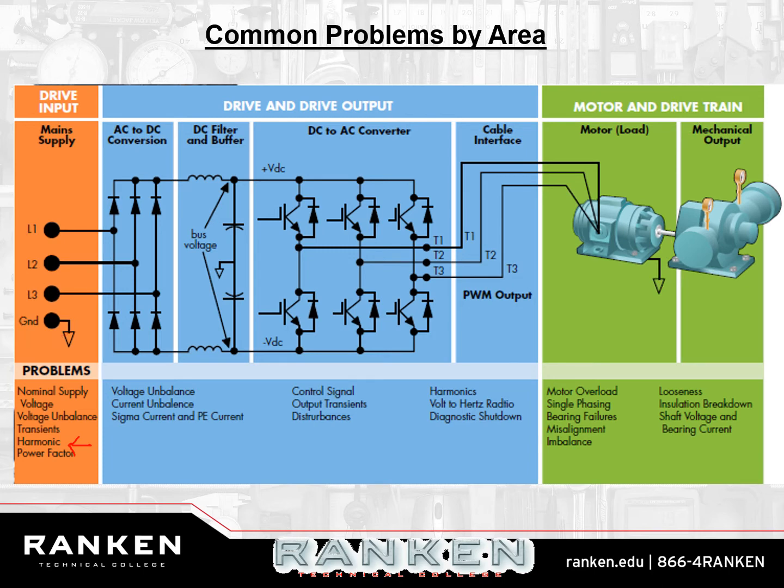The only thing that can stop it then are the little things, right? The actual control circuits. The control signals are the only other thing that can keep it from going. The drive isn't putting out power because somebody hasn't pushed the button, or somebody already did push the button, or somebody pushed the button at the wrong time, or the button is broke, or the switch is broke, or the photo eye is out, or the prox switch is out.